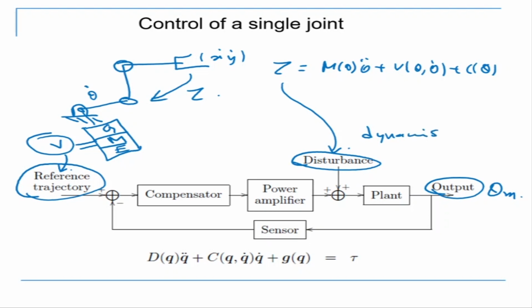So what does this basically mean? This means that if I'm trying to move in this direction, the dynamics will try and oppose that motion. Or suppose one joint is moving like that, and these two joints are not moving. This joint is not moving, this is not moving, but just because theta 1 dot and theta 1 double dot are there, these will be subjected to forces and moments. That is a disturbance on the controller, because the controller understands that the joint is not moving. It's holding the position at that angle, and yet it requires additional torque because this disturbance is coming from the first joint, which is disturbing the second and the third joints. That is the meaning of what this does.